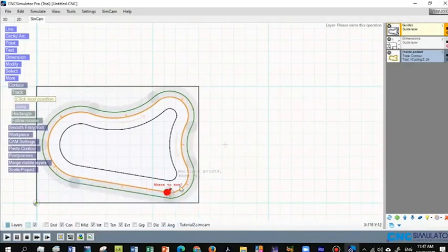So the contour that we talked about in chapter 2, I mean, it's like generating multiple coordinates for the spindle to go through in order to create the shape. And when you finish creating the contour here, you are going to see the code for this program. And this CNC code, if the workpiece is suitable for this one, can be easily generated.